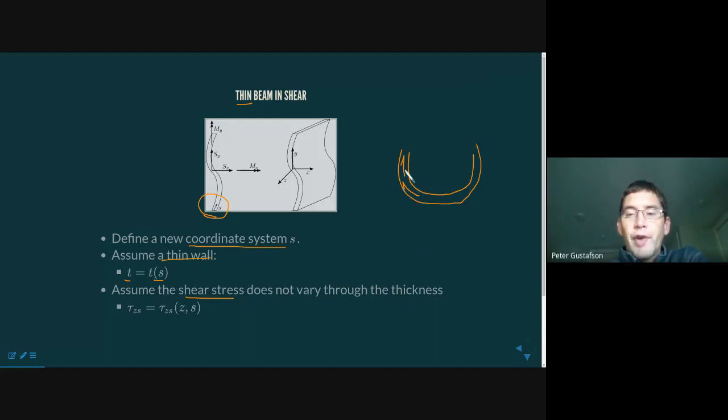Okay, that shear stress that's occurring, we have repeatedly referenced these loads that beams carry. That is the axial force P, the shear force S, the moment M. Those all were resultants. That means that it's the integral over the entirety of the area of the cross-section. In order to have S be non-zero, the shear resultant be non-zero, we have to have shear present on the cross-section. So this is what I'm really talking about now, is the shear stress that's present at a position S.